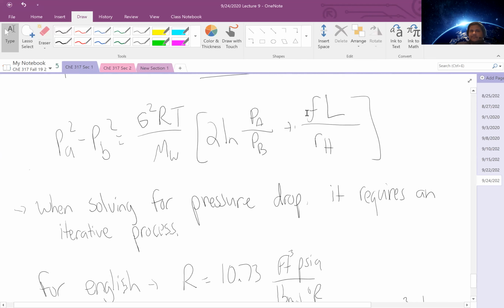With adiabatic, a lot of times we're considering that max conduit length, and for isothermal frictional flow, we look at things in terms of a pressure drop. And we can also consider a max conduit length in this system by setting that PB value to the asterisk condition value. So PB is equal to P asterisk, L becomes L max.